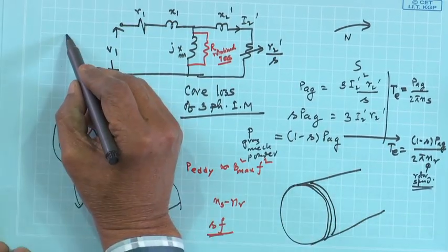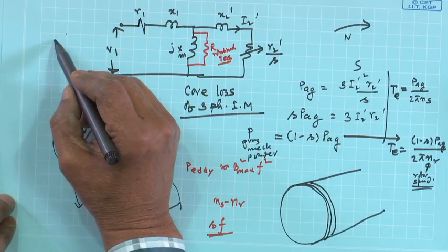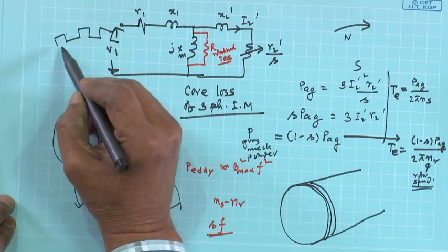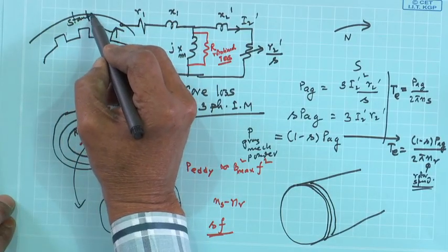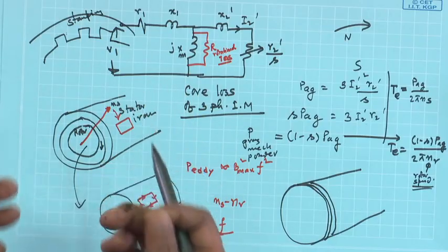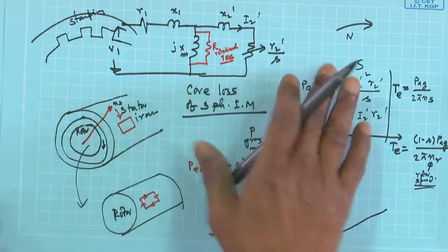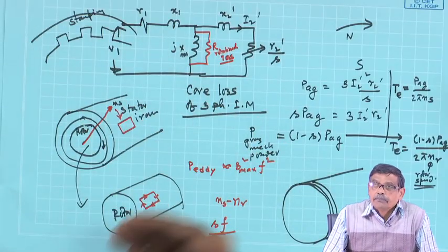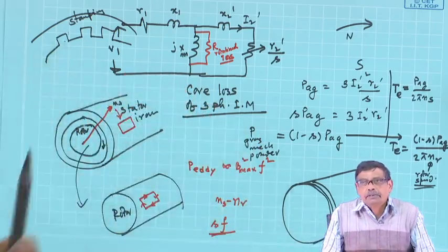For example, if you have a rotor, say stator block like this, stator iron, these are called stampings, thin plates, few millimeter thickness, flat plates like this here, anything not broad. So, thin plates of circular plates, slotted circular plates you take, which are insulated from each other by a varnish coating and stack one above the other to get the length of the machine.